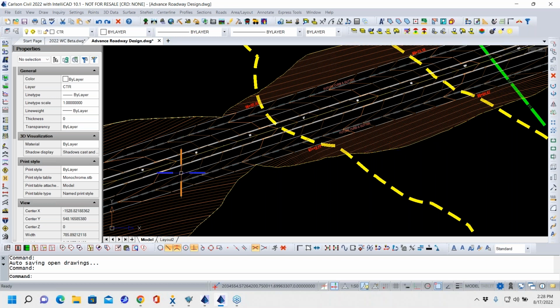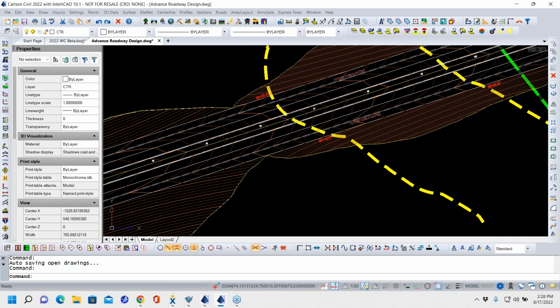So in order to do that, you have to create a, let me see here. What is that thing? I need to see this. There we go. So it's basically saying, all right, I'm coming from 5-to-1, even though this is in a field slope. But between this point and this buffer line, transition from 5-to-1 to 2-to-1. And that is what I'm going to show you how to do right now.